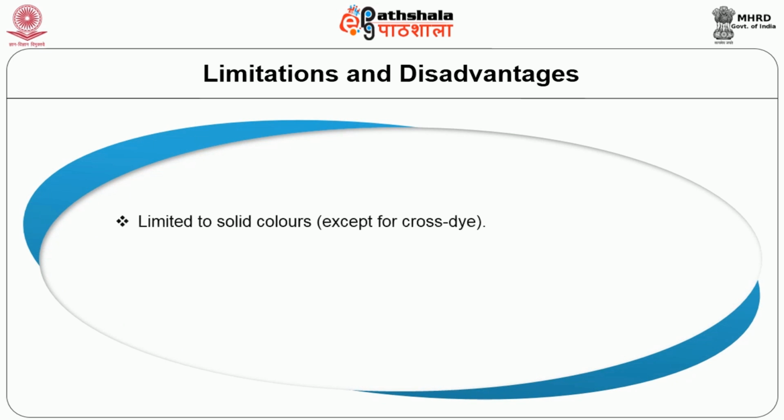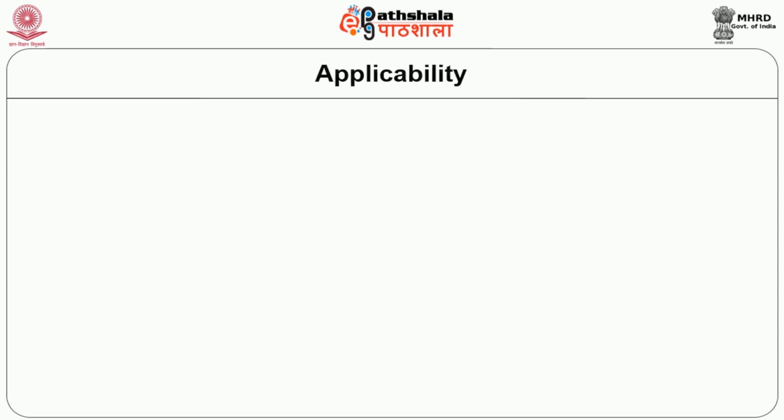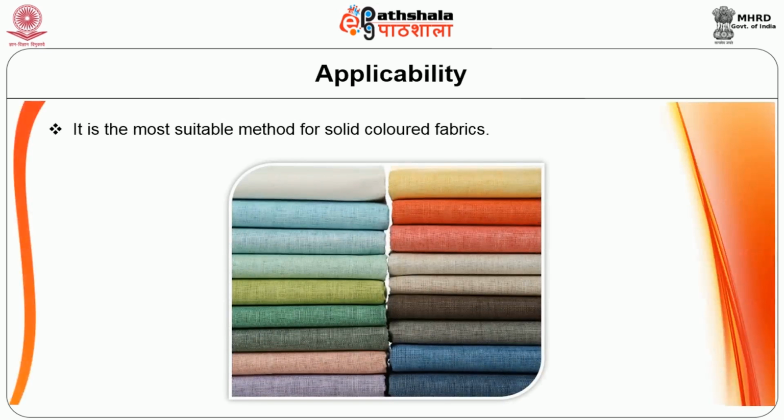In tightly twisted yarns and heavy woven fabric, dye penetration may not be good. Considering the applicability, it's the most suitable method for solid colored fabrics.